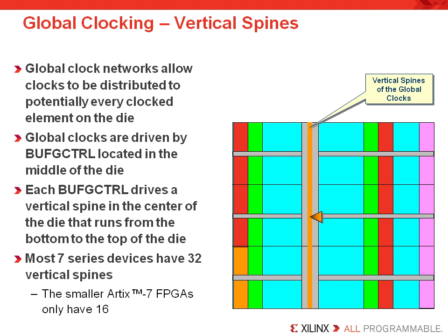Now the routing of the clocks is handled by the tools, so don't get preoccupied by these details. Now please note that when I say a BUFG, I really mean a BUFGMUX or a BUFG control primitive, and we'll talk more about those later. The BUFG was originally just an access point to low skew routing, but the BUFGMUX and the BUFG control have other features that we'll talk about later on.